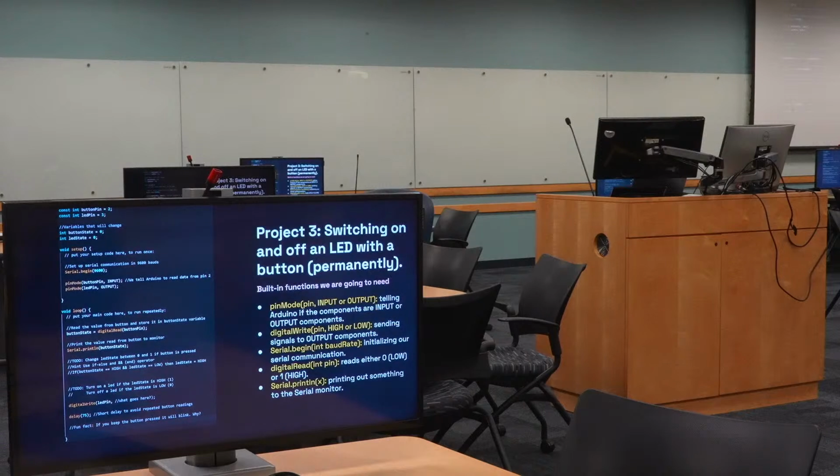Okay. It's not turning on. I think because the wire is not in the same column as the leg, the black one. Is it supposed to be the same color as the LED? It should. Let's see if that makes much difference.